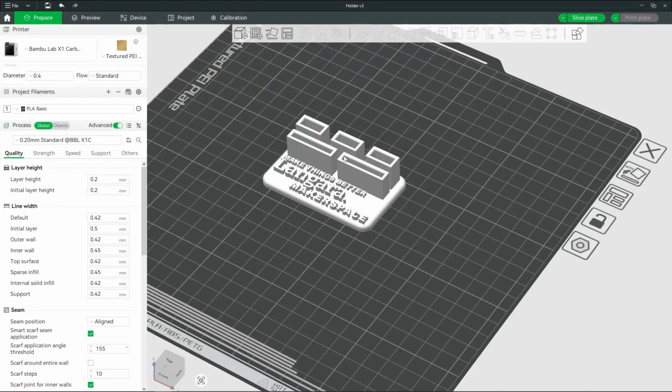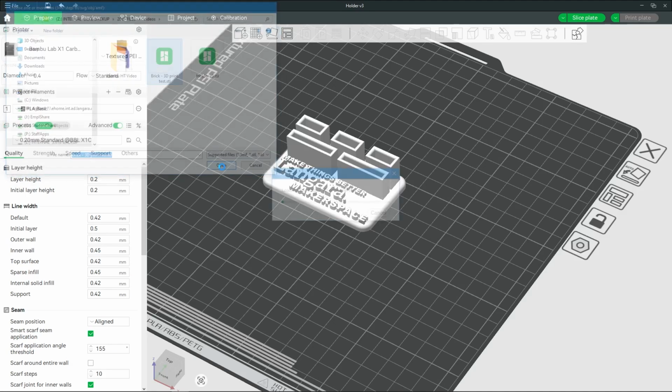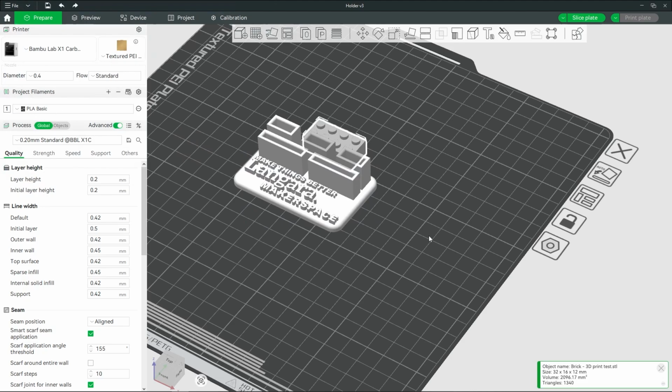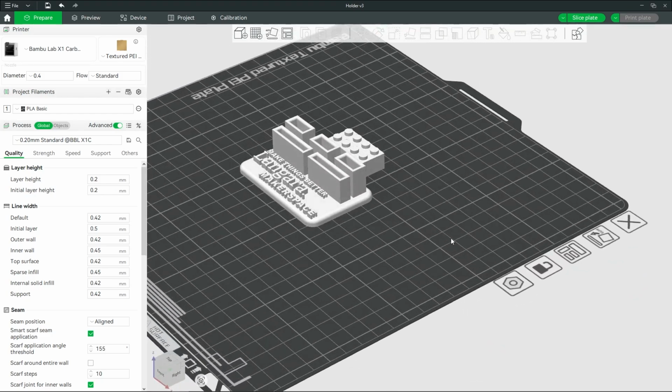Now, you can bring in multiple mesh objects. You always want to save as separate STLs, but just click on the import again, click on your other STL, and it'll come in. Now, at this point, you do want to move it, so select the move command and move it at least a 1/4 inch away. We get more into the move command in a bit.